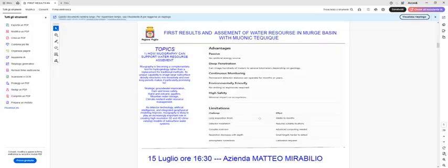Muography is becoming a completely new tool for hydrogeological mapping and monitoring, rather than other surface techniques like geoelectrics or magnetometrics. It has unique capabilities to image large subsurface density structures with a non-invasive method, and over long periods is particularly promising for strategic groundwater exploration, dam and levee safety, karst and volcanic aquifers, mountain water storage, climate resilient water resource and management.